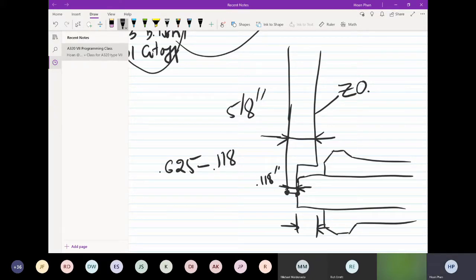And then if you're going to start right here, that means this face right here is right on the edge of the tip of the tool on the right side. That means if you call the next tool, the main spindle will know that it retracts back in order to make the zero right here for the next tool to turn. But then you will not have anything to face. So I will put another minus .5 right here. It's just because I want to leave some material for the turning tool to come back and face it.